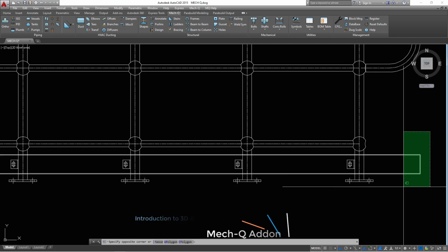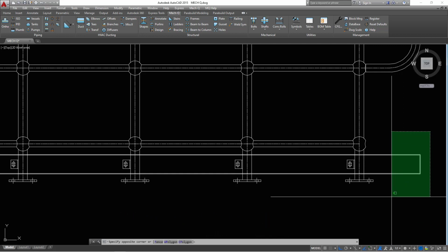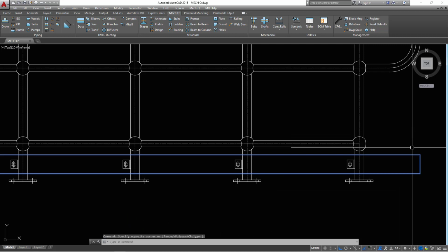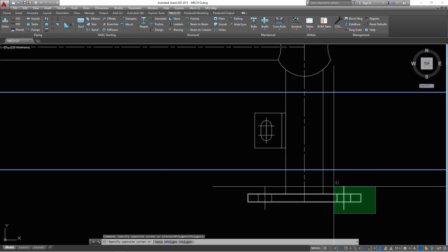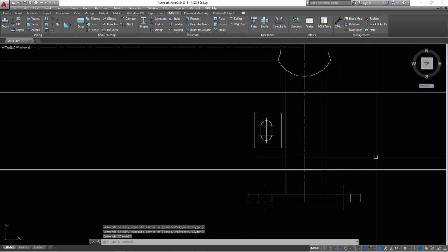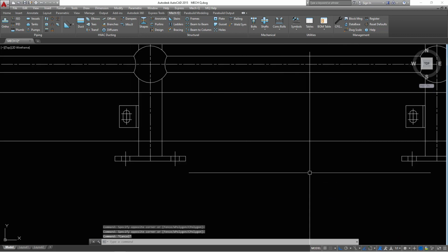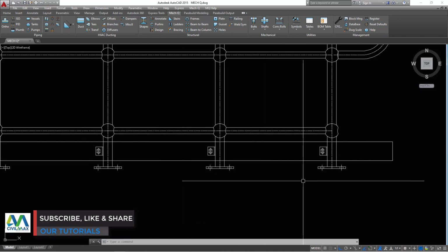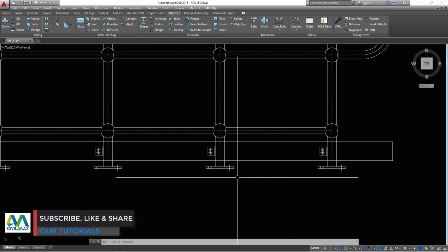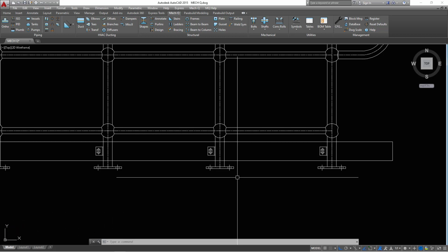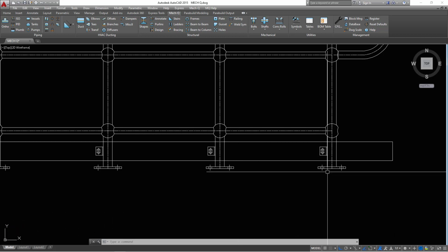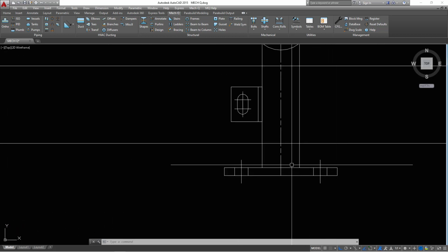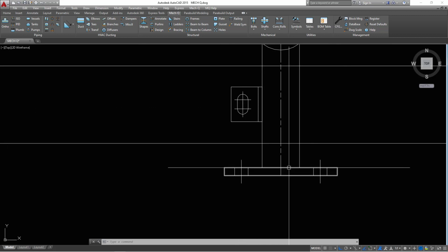In this case you can see the kick plate here. We have the kick plate there, and we have the plates at the bottom end here holding the stanchions to the beam that is suspending our platform, because we placed a choice on a platform type of handrail. So these drawings generated are scaled.